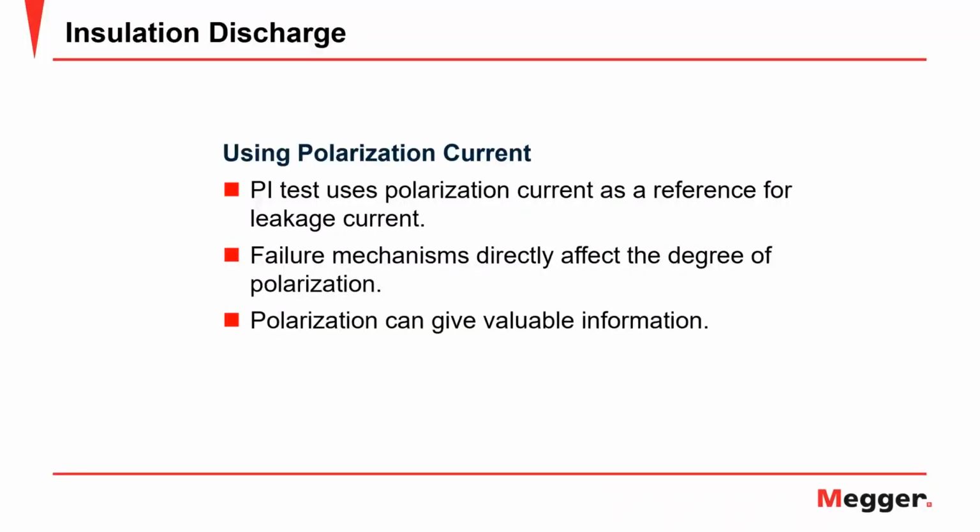Okay, now this gets a little dicey here. Now we're going to go to the dielectric discharge test. And I have to kind of skim through this because it's fairly complex, but we've been looking so far at polarization currents and what they can tell you, and you can get a lot of effective information out of that. Dielectric discharge uses the reverse and looks at depolarization, or discharge, of the stored charge on your equipment.